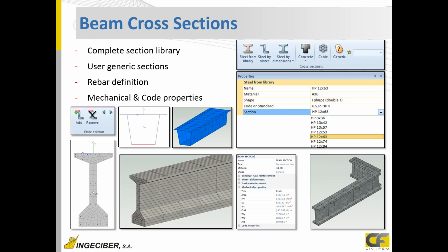For the case of concrete, we can define a 2D mesh of our section. We can set rebars, okay, reinforcing steel inside, using bars or using an amount by separation, using different diameters of bars, and then use this section to mesh our line. Okay, all these figures show beam elements. Well, all the proper mechanical properties of the section will be automatically defined and calculated.